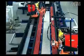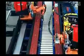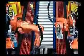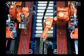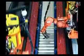In terms of production technology, the most difficult part of the production process is the welded connection between the web and the flange sheets. Perfect fit of the weld seams is achieved by laser metering and recording of their exact course for the welding procedure. The robots alone execute this measurement, as they won't rely on anyone else but themselves in this. For tracing the course, they move back and forth along both sides of the beam.